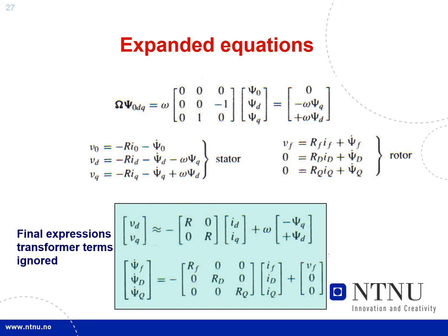Now, one could discuss these equations a little more, and if we write them out, we see the equations here for the stator, and very often what we do is we neglect the rate of change terms here, because they die out very fast, and we have then 2 equations describing the stator voltage, and we have three differential equations describing the flux linkages in the field windings. And this is with the damper winding models.